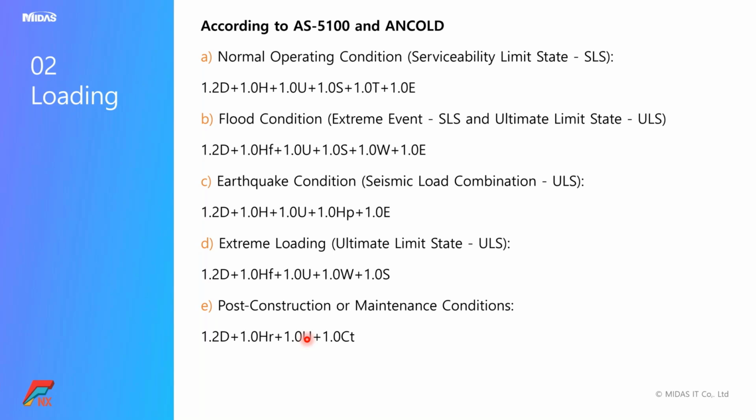the factor of safety against sliding may vary for earthquake load as well as for the normal operating condition. But in the load combination as per ANCOLD guidelines, the factored load is directly applied onto the dam, but the factor of safety against sliding and overturning will remain the same because the loads are the ones which are factored here.